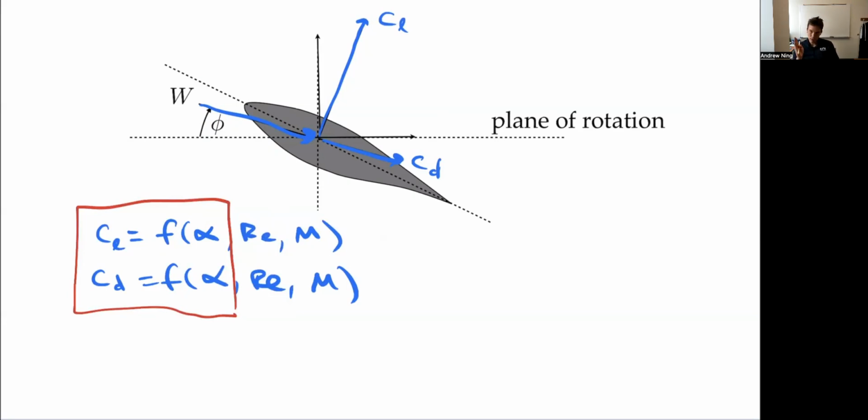Okay, so I've got angle of attack, so I can look up, compute lift and drag, right? And again, this may be something I've already computed for an airfoil. I know what my airfoils are, so I can pre-tabulate that data and just fit a spline. So this is a very quick, easy calculation. But as we'll see, what I want is not necessarily lift and drag. I'm going to need these forces, CN and CT, my normal and tangential forces.